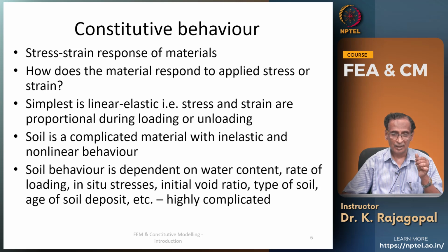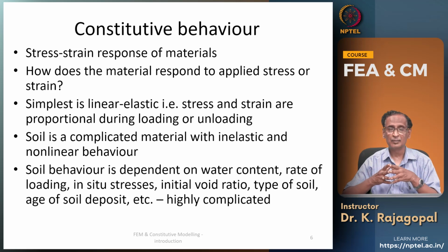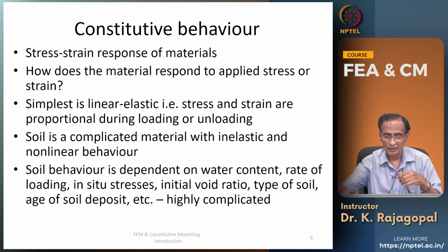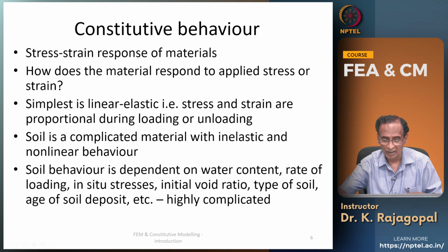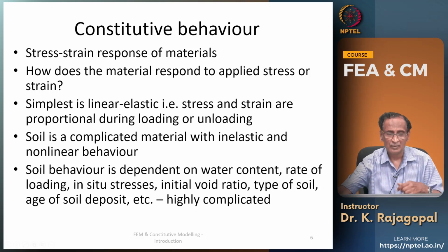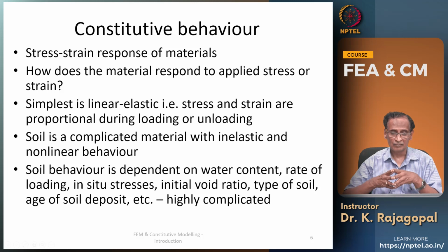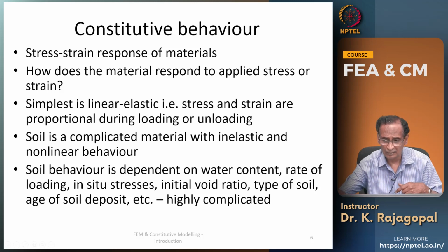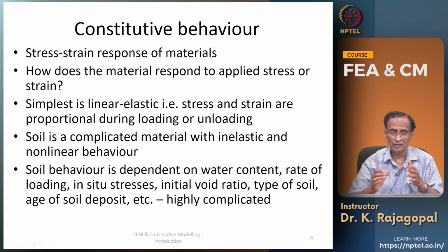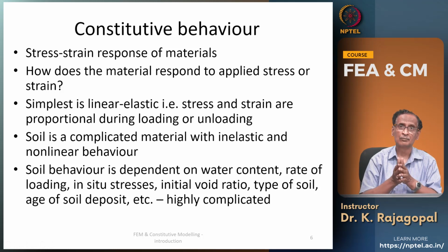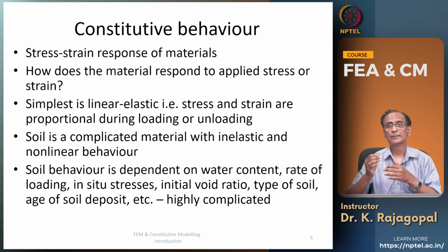Also the soil behavior is dependent on the water content, the rate of loading, the in situ stresses, the initial void ratio, and the type of the soil, whether it is a loose sand, dense sand, normally consolidated clay, or over consolidated clay, and so on.